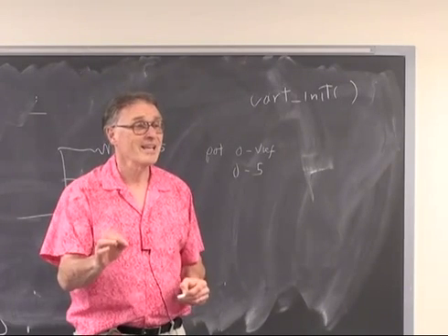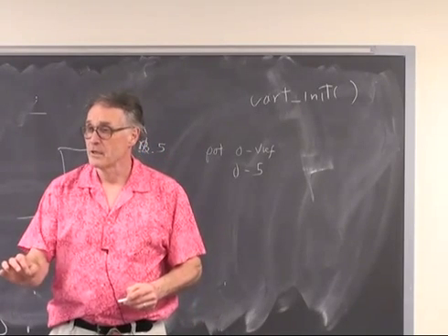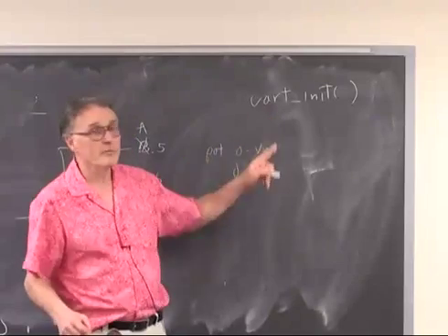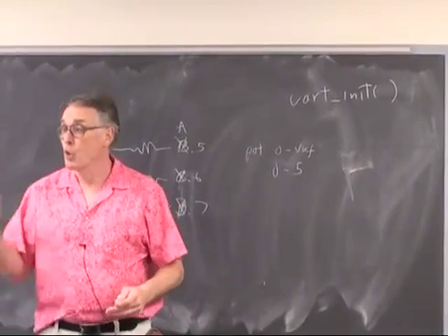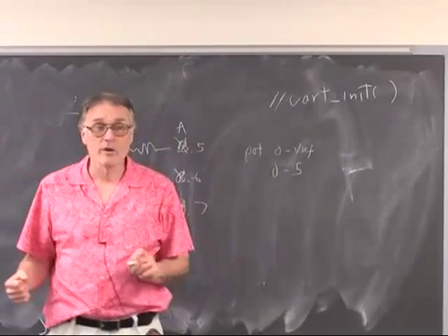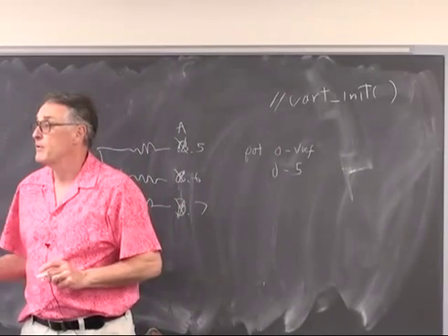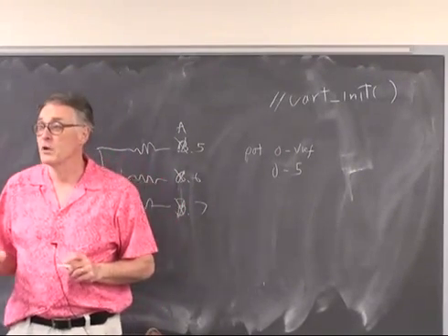They are dedicated to the UART, and they will not work with the keypad. So if you just leave this in here because you cut and pasted code from Lab 1, it won't work. You have to comment this out and all references to the UART before you can use the UART lines D0 and D1 for the keypad.